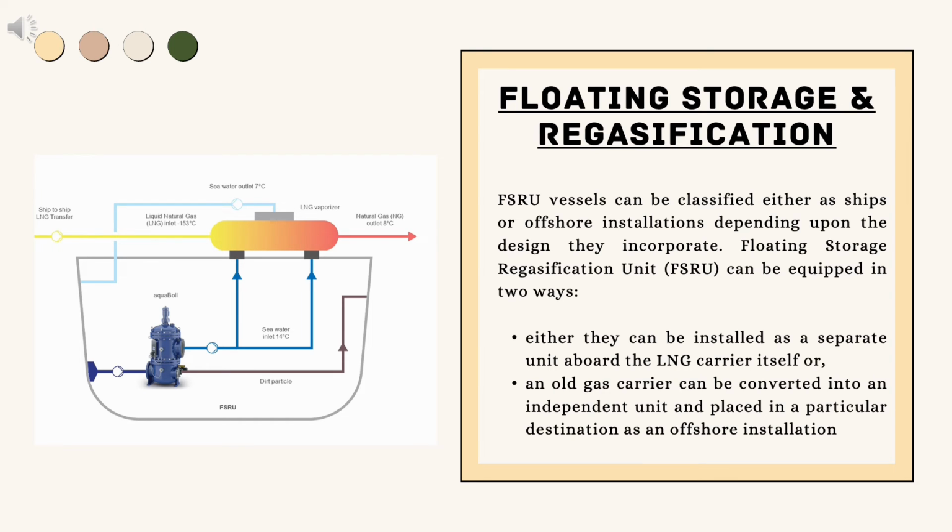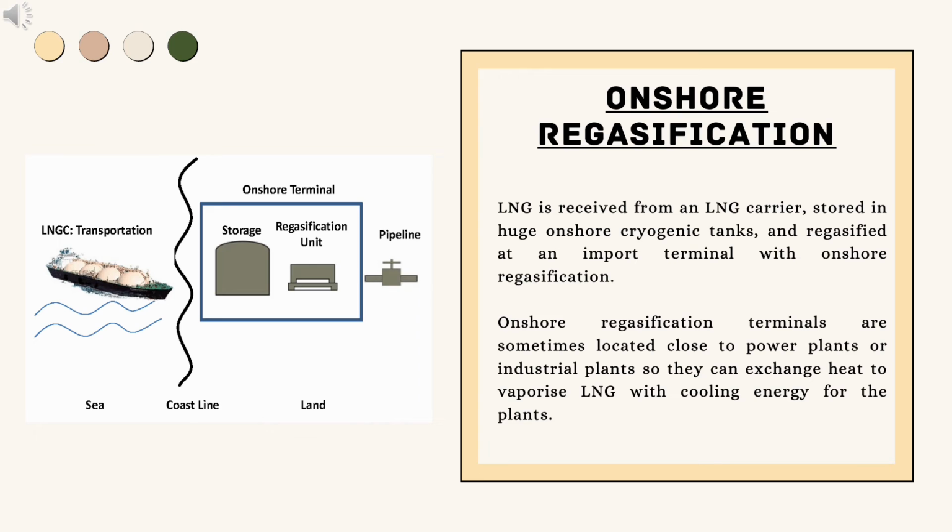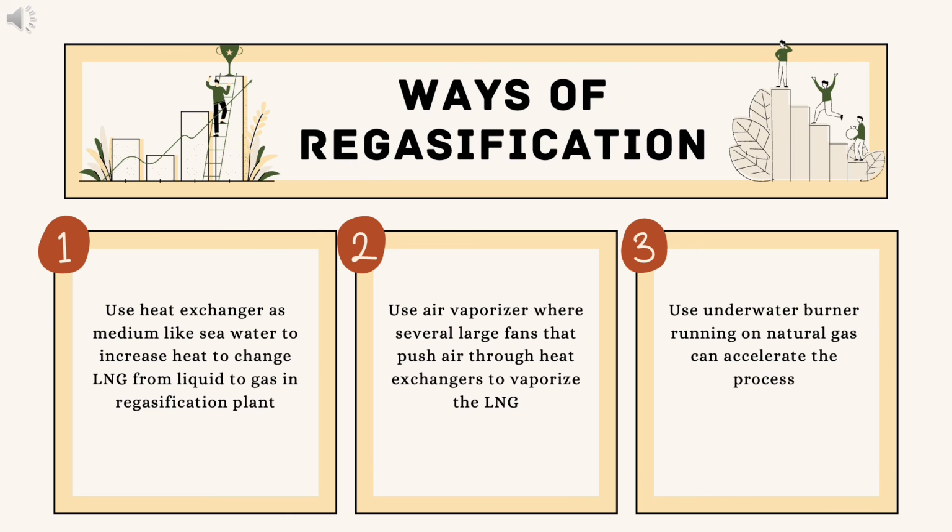as FSRU. Onshore liquefied natural gas regasification process is a process of producing and supplying natural gas, the final product, by receiving liquefied natural gas from liquefied natural gas carrier and storing it in a cryogenic liquid state and then vaporizing it through a vaporizer. There are three ways of regasification, of which the first one is